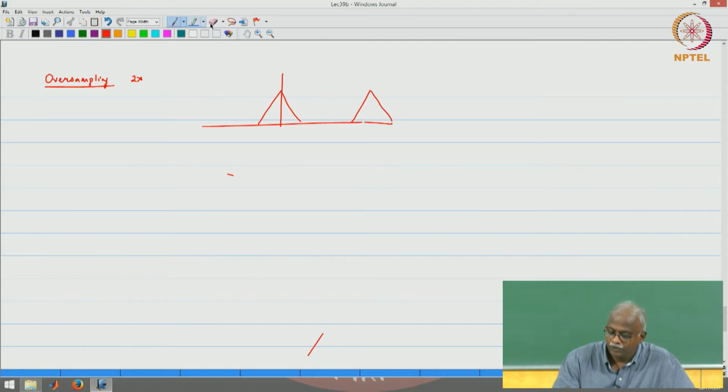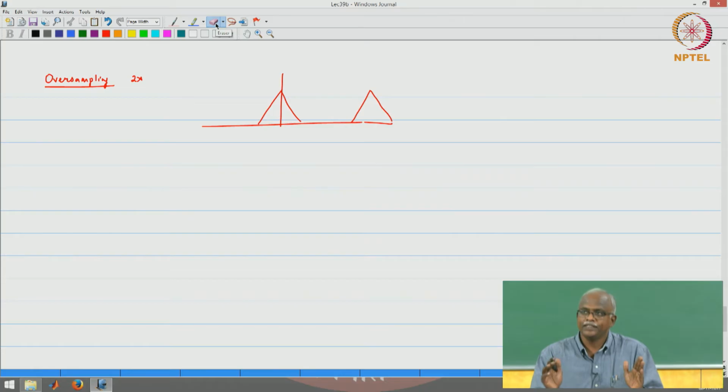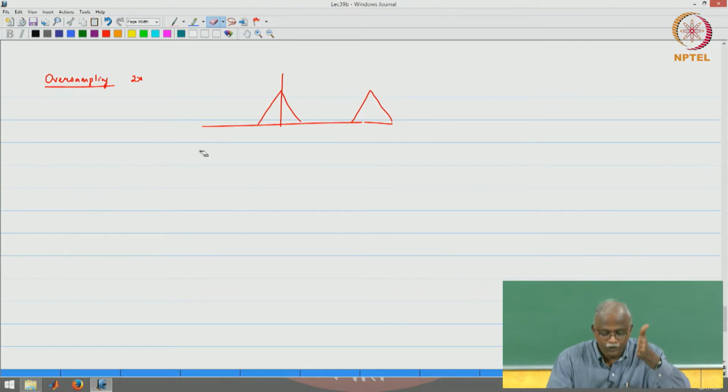oversampling. Now this is where you will start to see the benefits of what we have discussed. When you have quantization noise, it is uniform and over the entire range that we are going to be working with. So anytime you have quantization noise, you have to worry about it. The reason we would go to 2x first and foremost, if you want to do sampling, would be to do anti-aliasing filtering. So you need to have anti-aliasing filtering before you do sampling.